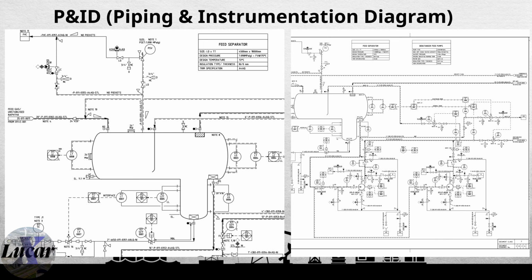A P&ID provides a wealth of detail, from feed sources and block valves to control valve types, instrument loop, control loop, interlock, ESD. You will find comprehensive piping specifications, including line sizing, materials, pressure classes, and insulation types, as well as details on blinds and their types.